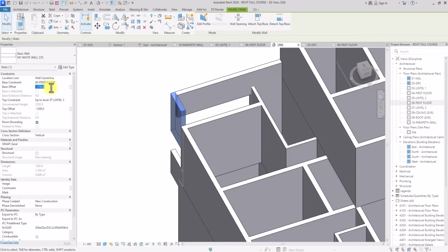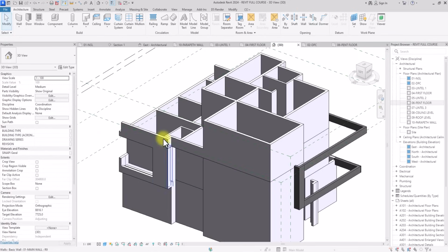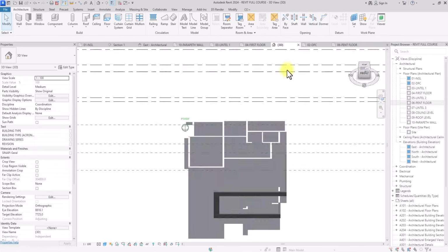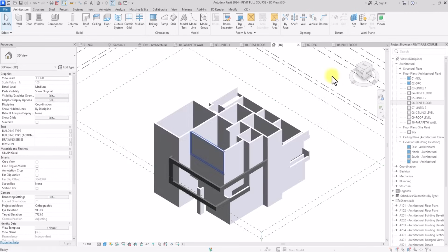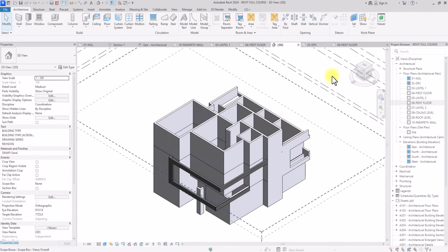Change this to minus 450. And I'm going to change this to 0. And I'm going to change this to paint floor. I might actually make some alterations here, but that will be for the future. So now I want to start working on the facade character and the structure. As you can see, I've not even started placing the windows or floors. I just want to get the structural outline first before I go into all those things. That is the way I preferably model.